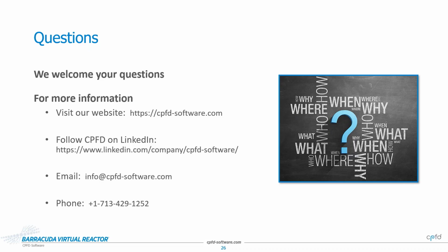And so the rotating gravity features will not enable that rotating geometry within the system. So just be aware of that. Really what we've enabled here is that the entire domain is moving according to some variation in the gravity vector, rather than the walls of the domain moving relative to something inside the domain, like an impeller or a mixer. So yeah, just be aware of that.